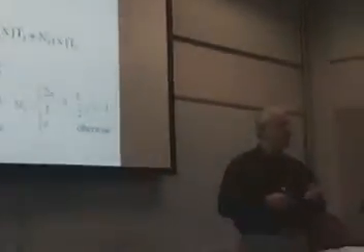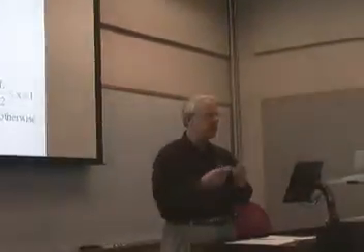The end result of doing the calculus of variations and the method of weighted residuals is that you get the same equation at the end of the assessment. Then you're free to use whatever element shape you want, whether you did it from calculus of variations or the method of weighted residuals. But in the method of weighted residuals, you can take any equation. It doesn't matter. Take that equation, you integrate it, multiply it by a weight, set it equal to 0. That's all there is to it.